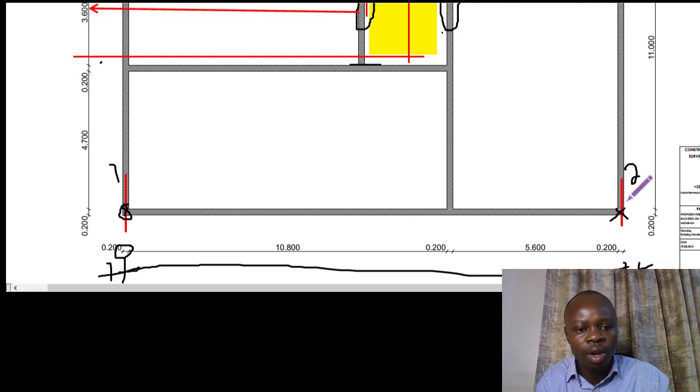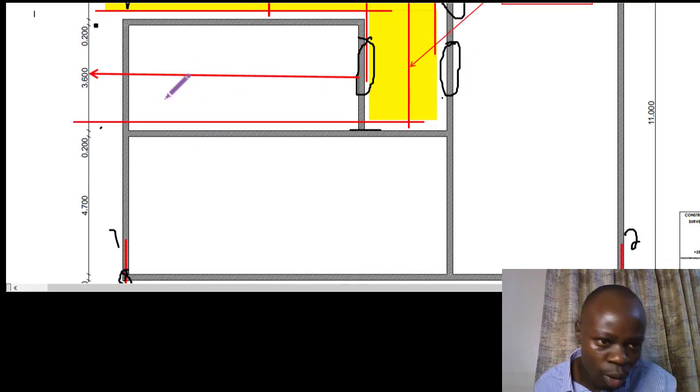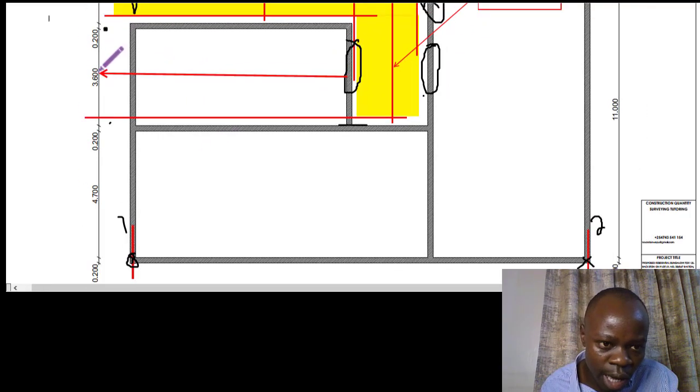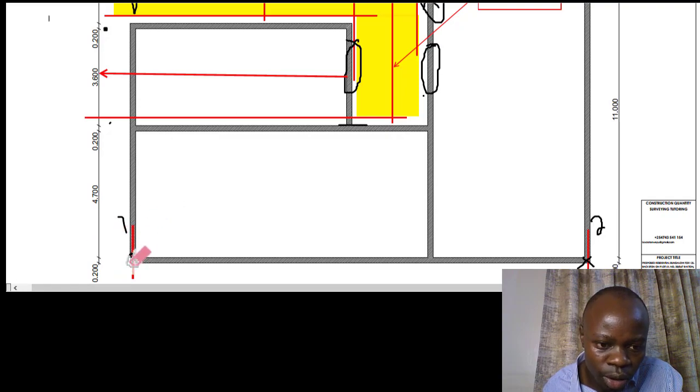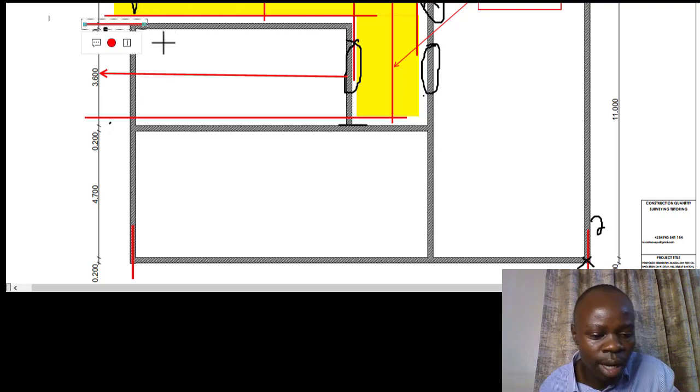It means you've taken 100 on one side and 100 on the opposite side. Okay, when you come to this other width, for instance the one that is to the left, what will happen is you also took the full length from top to bottom at the external faces of the external wall. But now we also need to adjust so that we have it towards the half, towards the center of the wall. Okay, and this is how it happens.